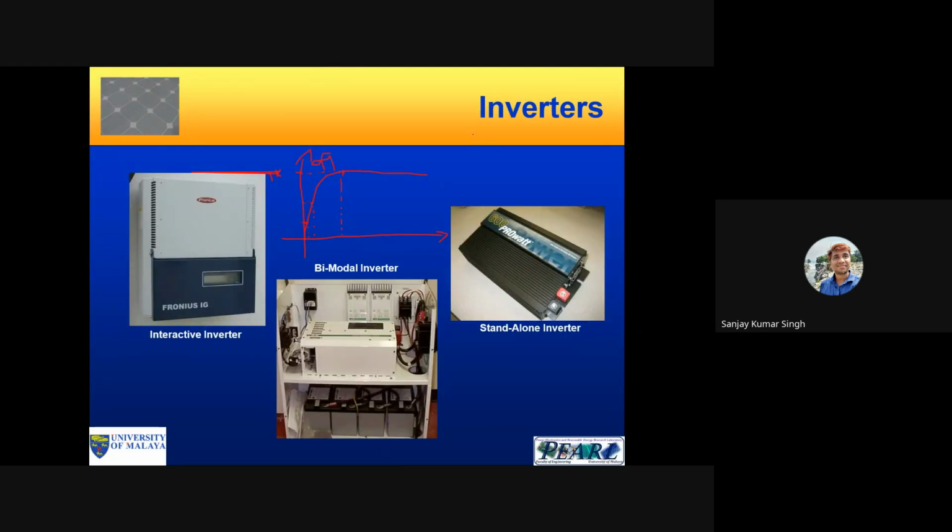Sir, I understood the concept which you explained. Just one thing: what is the short-term overload capability of the inverters? I agree with you, because not all systems have peak generation, so it doesn't make sense economically to go for the same size, which we hardly use. But if some inverters see peak power from the PV cell, probably for a very short duration, then if we are sizing 20 to 30% low, it has to withstand that as well.